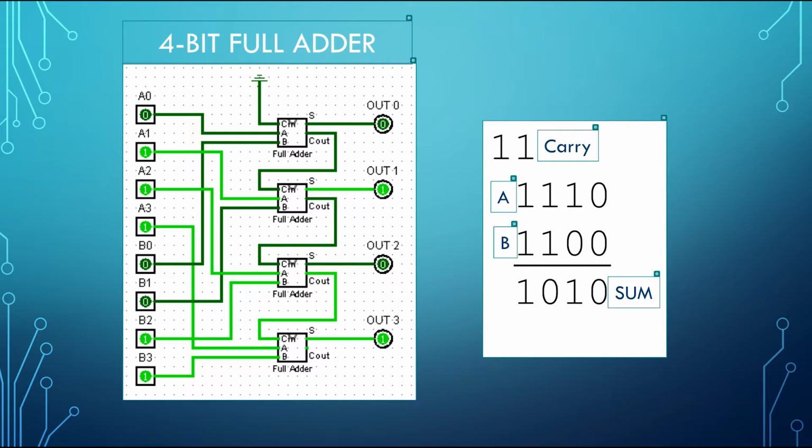For example, two zeros make a sum output of 0, and no digits are carried. 1 and 0 make a sum output of 1, but there is still no carry-out. Two 1s will give us a sum of 0 and a carry-out of 1. Finally, if there are three 1s in a column, the sum and carry-out will both be 1.